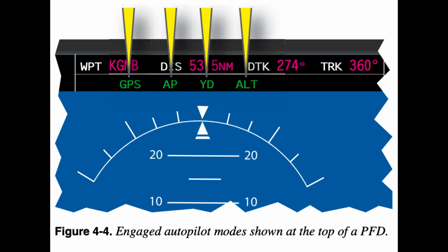Determination of control movements required to achieve goals. Suppose you wish to use the Autopilot/FD to turn to an assigned heading of 270 degrees. The heading knob is used to select the new heading.